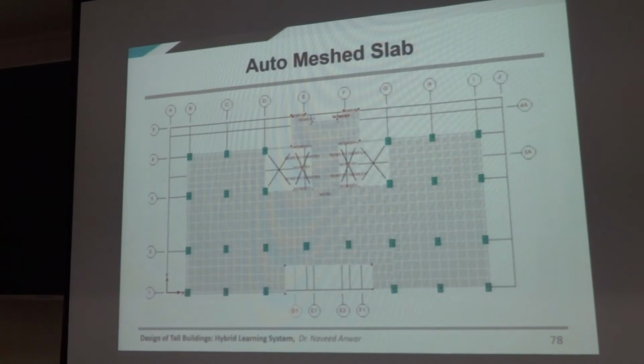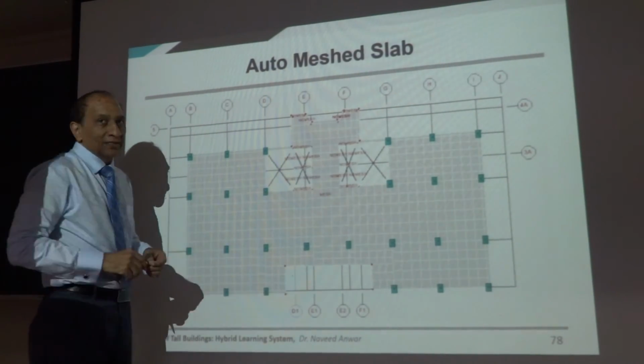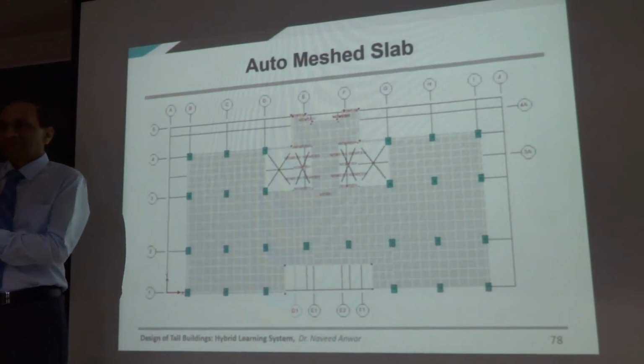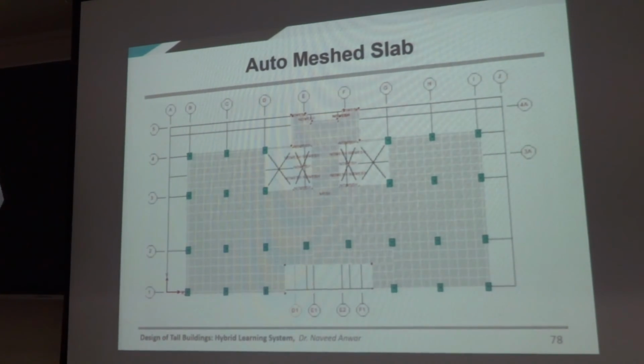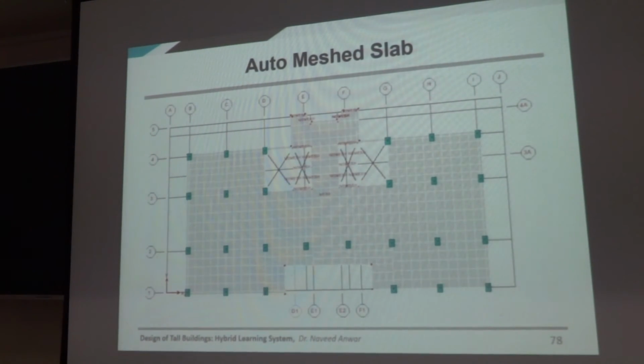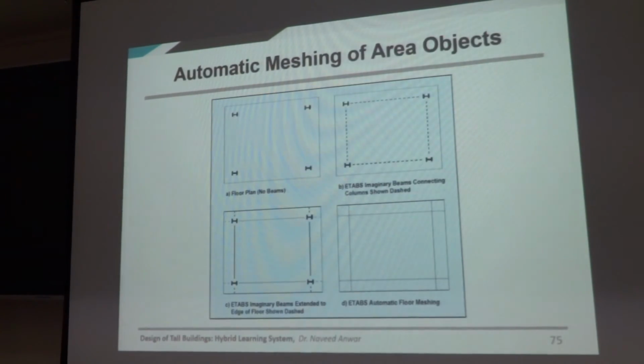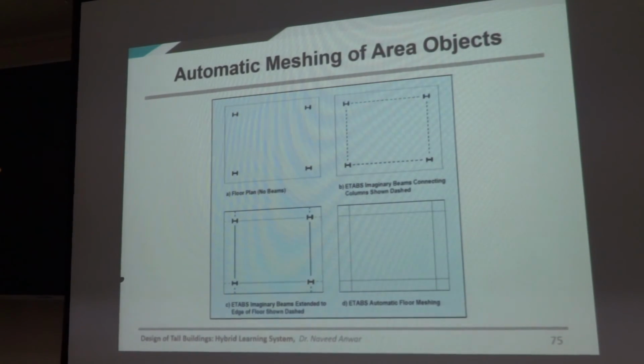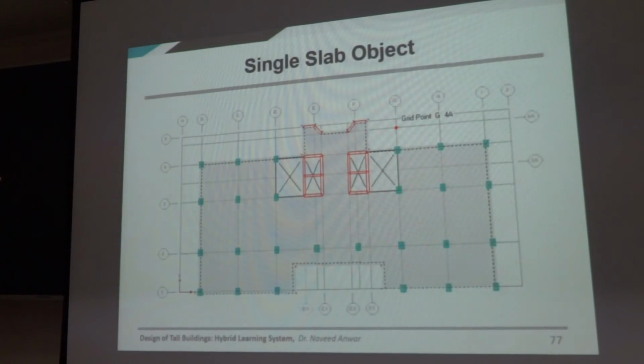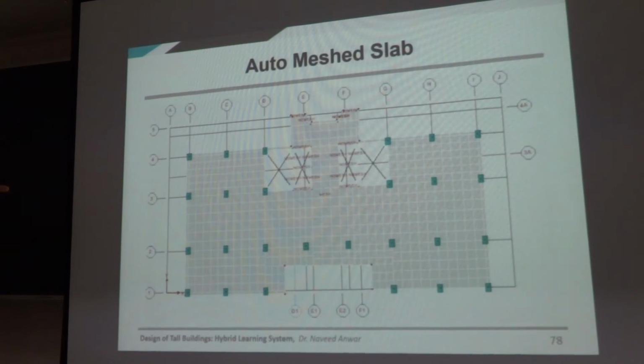That's why for slab design, we normally use another program which goes slab by slab, SAFE. And for overall analysis, we use a mesh which is not so fine, because we are not worried about the local deformation, we are only worried about the load transfer. So for load transfer, this level of mesh will be okay. But for calculation of the slab deflections and moments and design, you need this one, right?